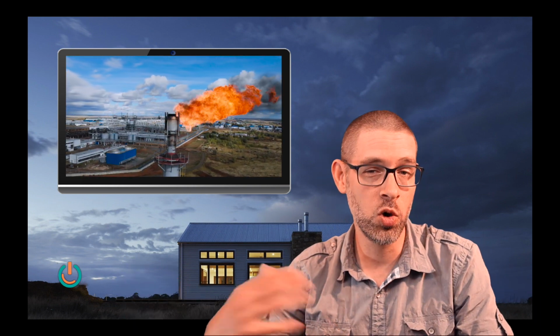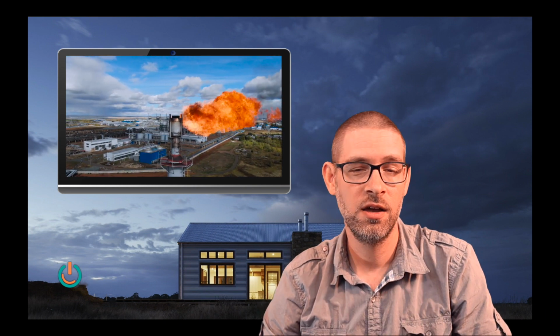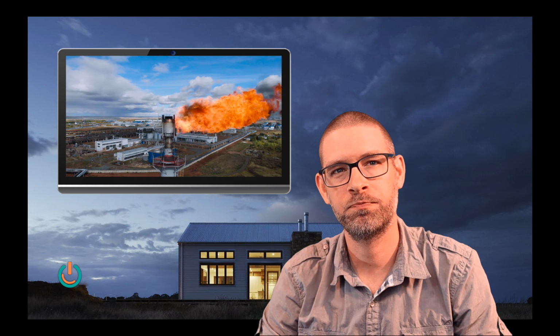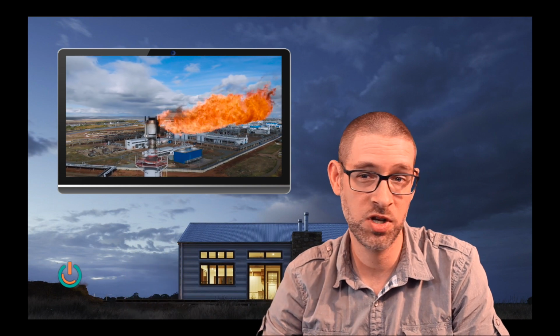It's more expensive to deliver these fuels on the backs of trucks to your home. And specifically with oil furnaces, they do not burn near the efficiency of natural gas or propane systems, which can use condensing technology. So most oil furnaces burn in the efficiency range of 80 to 85% rated efficiency. And so the price that you would pay to heat your home with oil is that much higher, because also the fuel cost is that much higher.